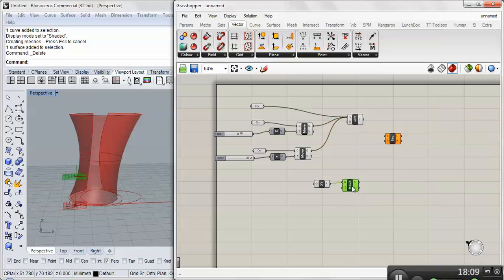Alright, so now we have our move, we have this empty vector, and here's where we're going to have to feed it a series. For today, let's say I'm going to do a 2-foot horizontal grid. So I want to make a series of numbers that go from 0 to the height. I move mine up to 30 and have a spacing of 2.